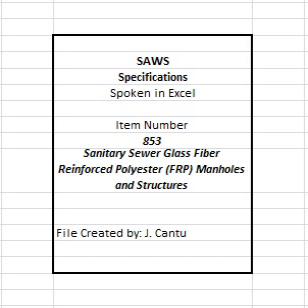4. Any manhole excavated for repairs or excavated for tie-in shall be encased with a minimum of 12 inches thickness of flowable fill to 1 foot above the top of the cone section to allow for the concrete ring encasement.